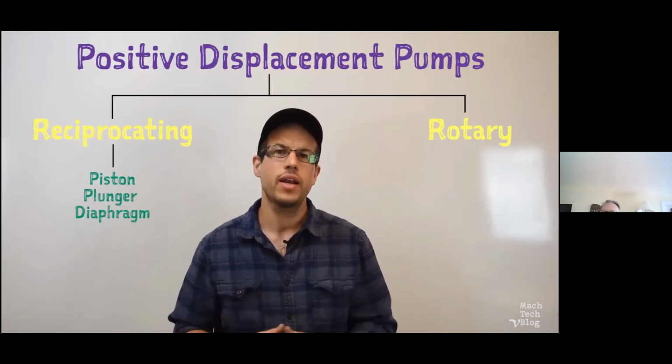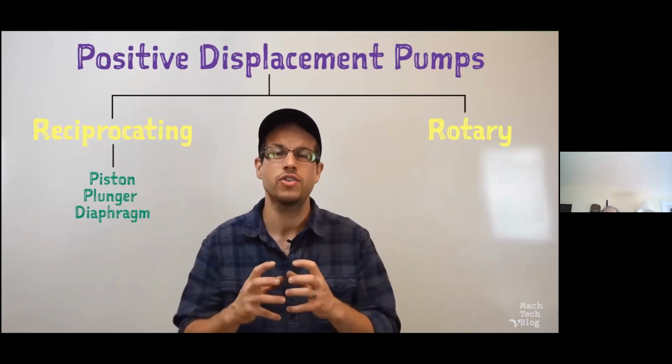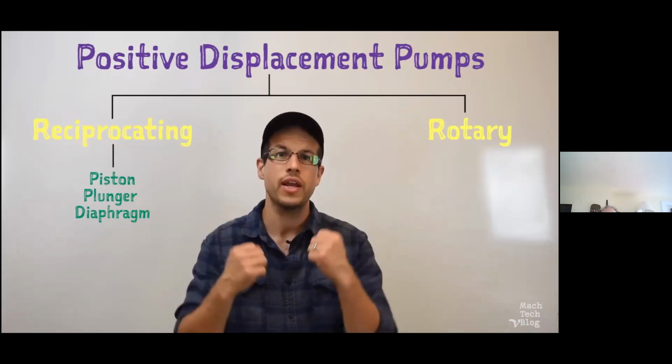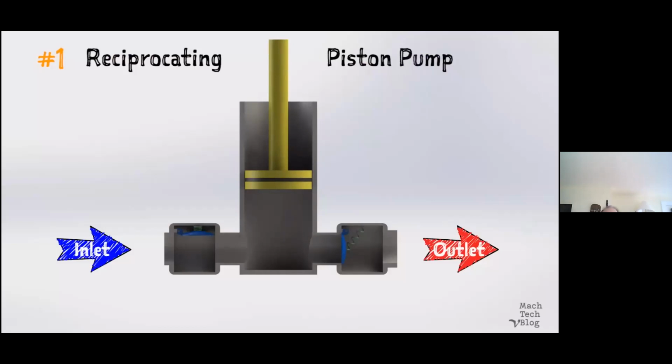Every reciprocating pump utilizes some kind of expanding and contracting chamber and a series of check valves in order to draw fluid into the pump and then direct it out into the system. To illustrate this concept, let's take a look at pump number 1, the piston pump.